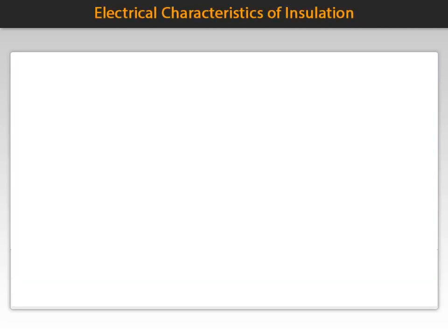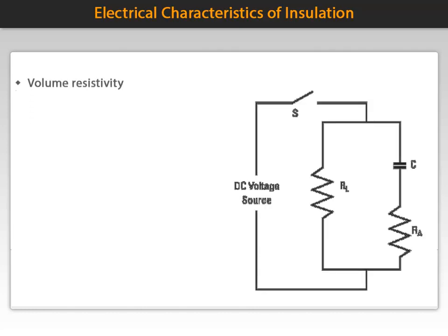Earlier, we looked at the important characteristics of insulating material. It is now time to look at the important electrical properties. First off is volume resistivity. Volume resistivity of insulating materials measures how strongly a material composition opposes the flow of electric current through a volume of cubic specimen. The lower the resistivity, the higher the conductivity, namely as the electric charges meet a weak resistance to circulation.